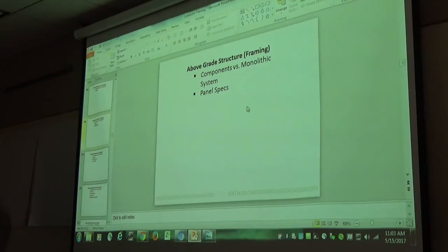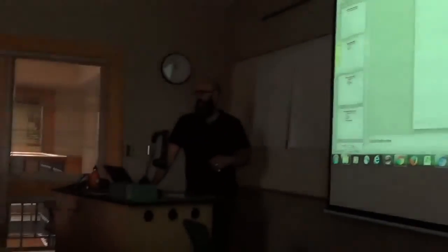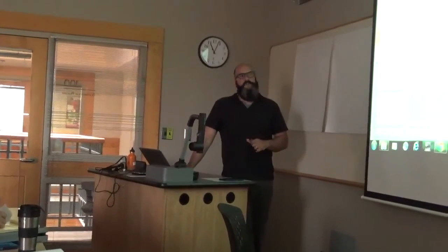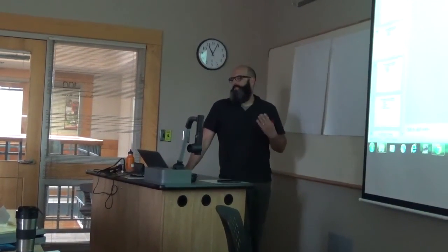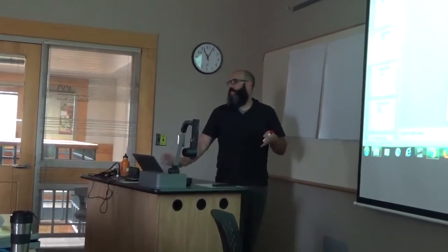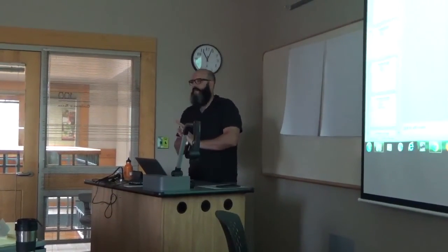Yeah. So that's the other thing: the panel thickness we're using is a product that they're already making that gets used for a rim board. Okay. So we're using a product that's inch and an eighth thick, which seems like an odd number, and I would agree with you, it's odd. But inch and an eighth thick. The panel is 860 pounds each panel. So if you think about lifting that panel, it's a pretty substantial weight. And we're taking these panels and laminating two of them together. Okay.